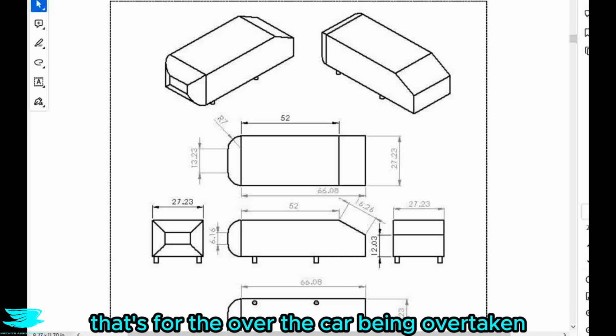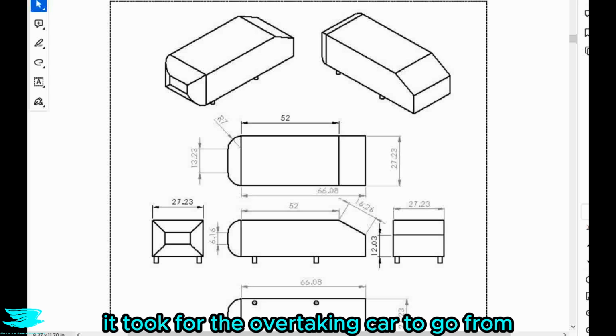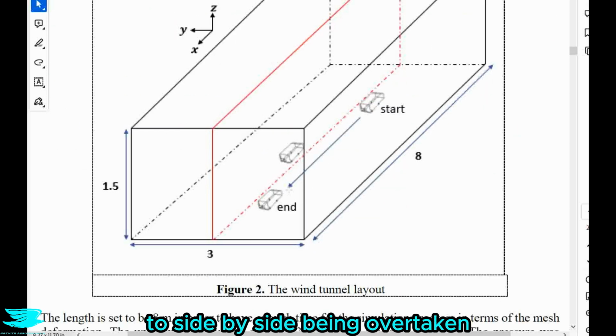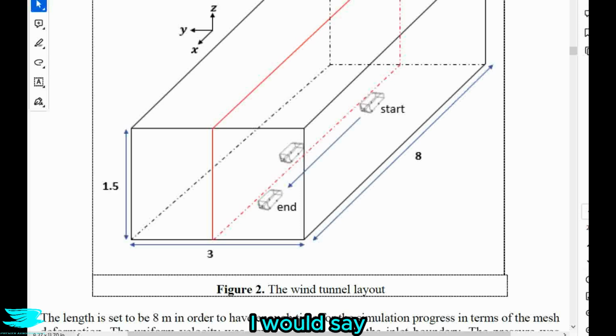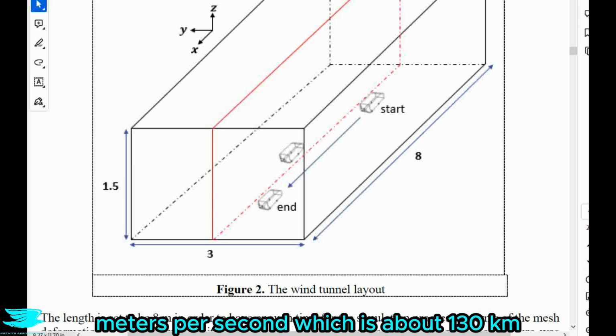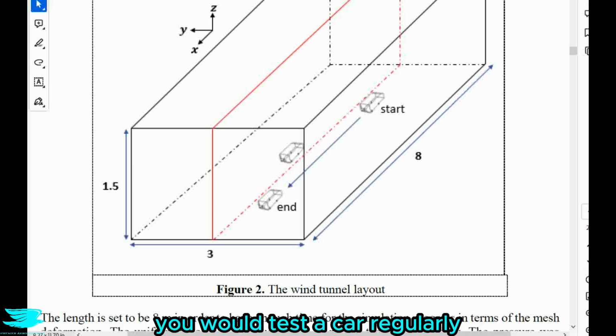Now that's for the car being overtaken. For the overtaking car, they don't seem to say exactly what the velocity of that car was. I can't find any exact number, but based on the approximate time it took for the overtaking car to go from its starting position in figure 2, to side by side being overtaken, which is about 0.5 seconds, I would say that the overtaking car is traveling at about 36 meters per second, which is about 130 kilometers per hour, so pretty fast. That's almost about as fast as what you would regularly test a car in a wind tunnel for the WLTP standards.